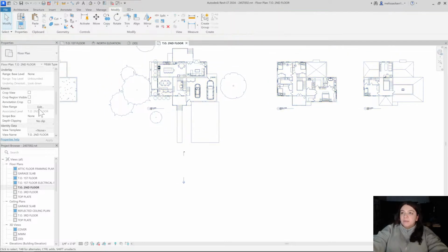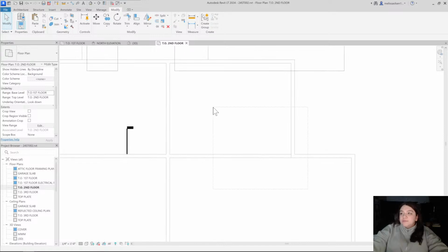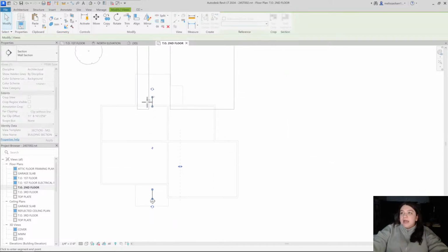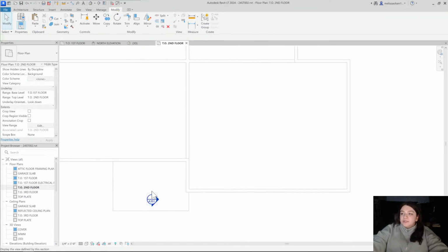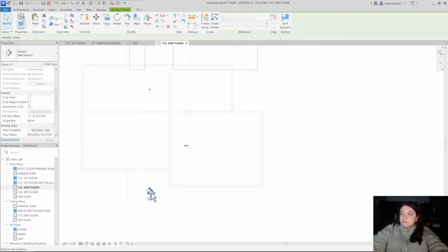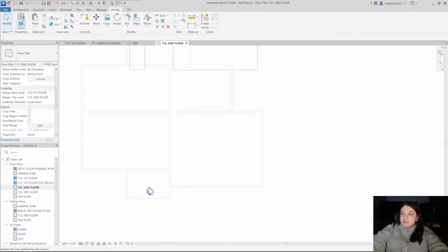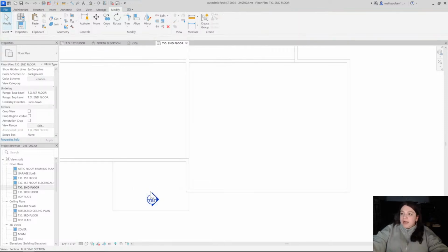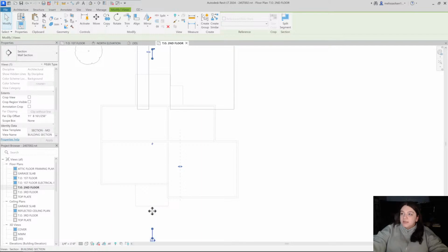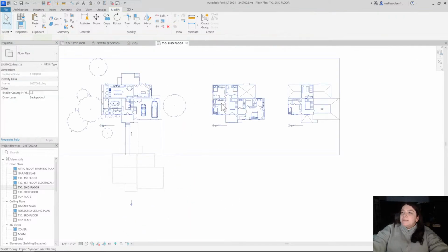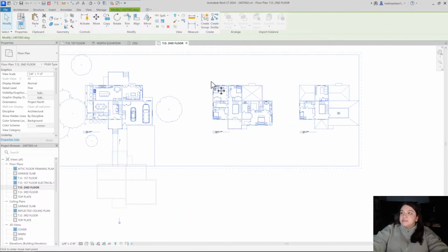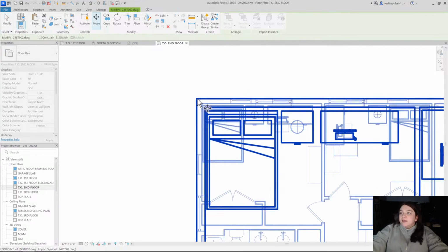I'm going to go over to my properties, and I am going to turn on the 1st floor underlay. So there's an underlay category. I'm going to say 1st floor, and now this portion that has been grayed out and I can't actually touch it is going to pop up for me, which is great. I'm trying to move this section out of my way really quick just by dragging it. So now I'm going to do MV, which is move, and I'm just going to pick a point